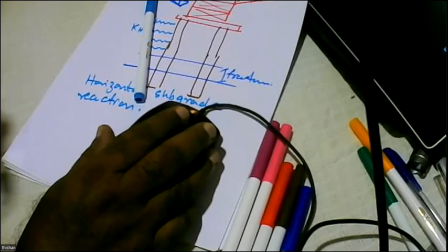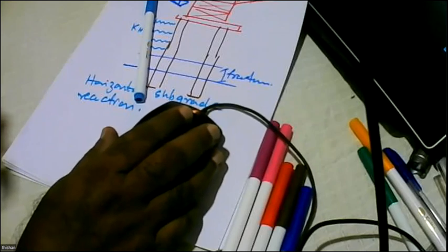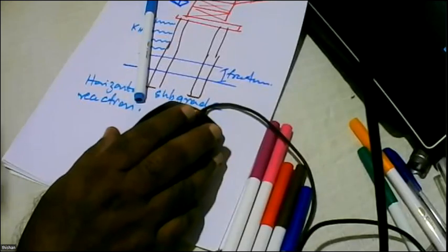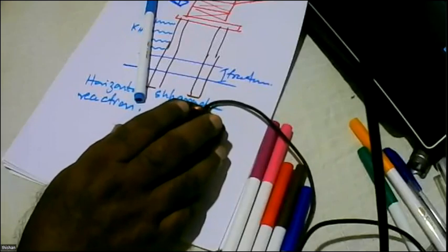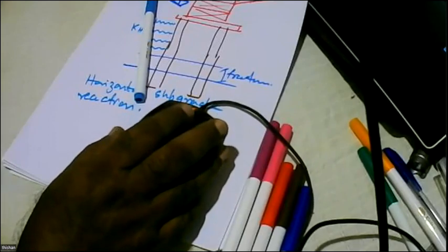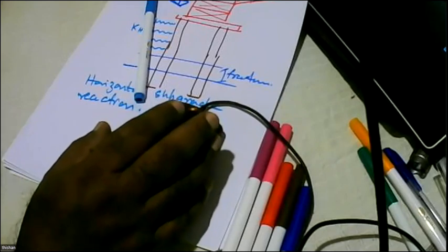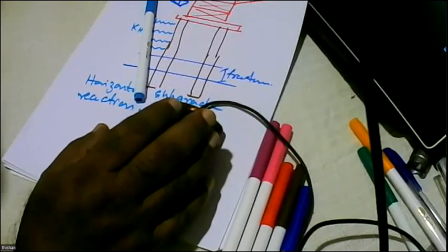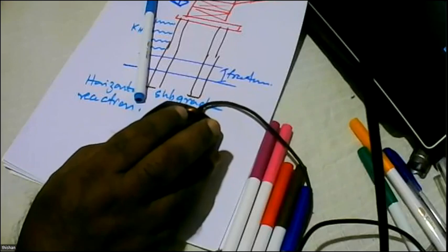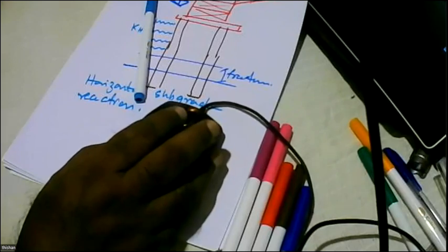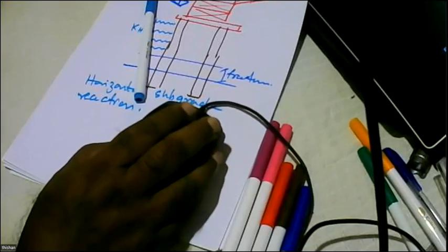So sometimes cohesion of soil is given as 5 times N, and I prefer to use 4.5 times N. But many geotechnical engineers use cohesion equal to 5 times the SPT value. But if the SPT is like 2 to 4, you have to be very careful, because sometimes the SPT that is reported may be misleading. When it is greater than 4, generally, you can rely on the SPT value.